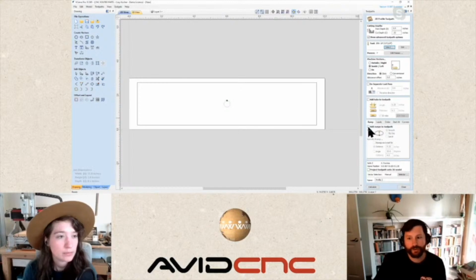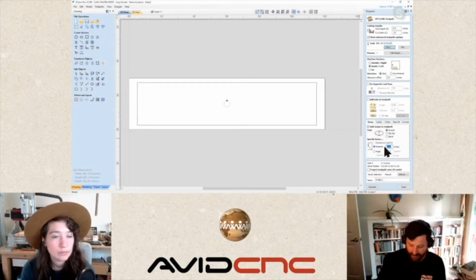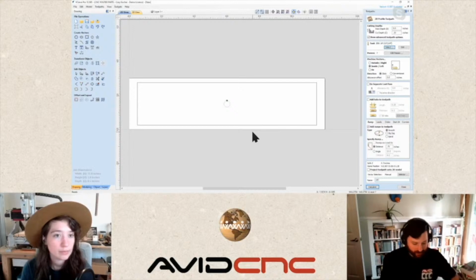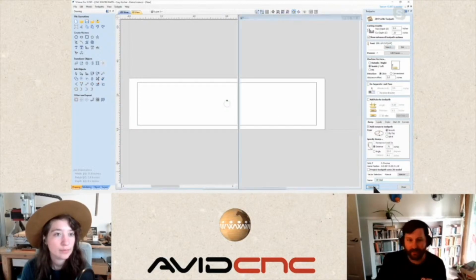Yeah, and so I do want to ramp this toolpath, and I want to ramp it at about the diameter times 3, or just under pi. And so it's a 1/4 inch diameter, and so that means our ramp distance is 0.75. And I'm going to call this CB1 because this is actually our CB clear, because this is going to be the area where we clear the area to create our counter bore. And so let's go ahead and calculate this.